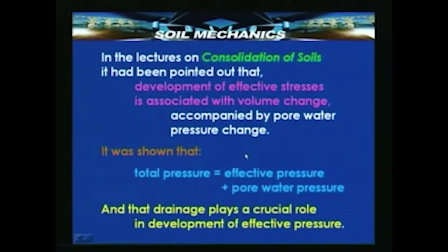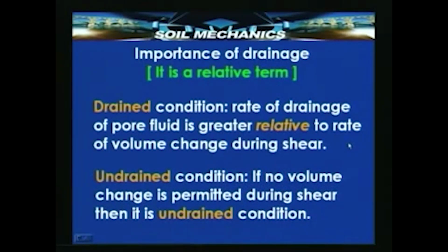Therefore, if we apply a shear force and do not allow volume change, then pore pressures will be developed. And the well known equation, that total pressure is equal to effective pressure plus pore water pressure, will be valid. Thus, drainage plays a very important role. And what is this drainage? Why is it important? It is important because actually it is a relative term.